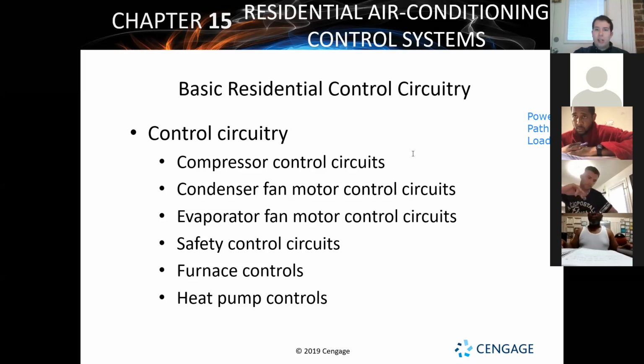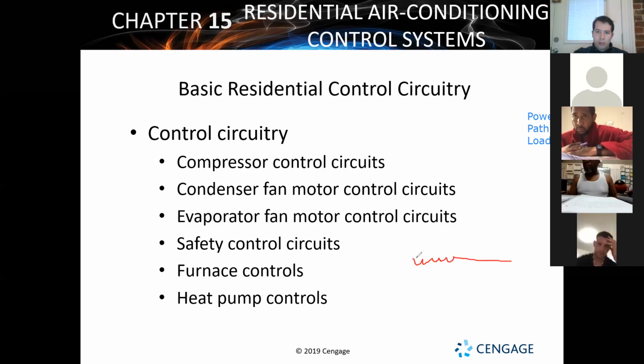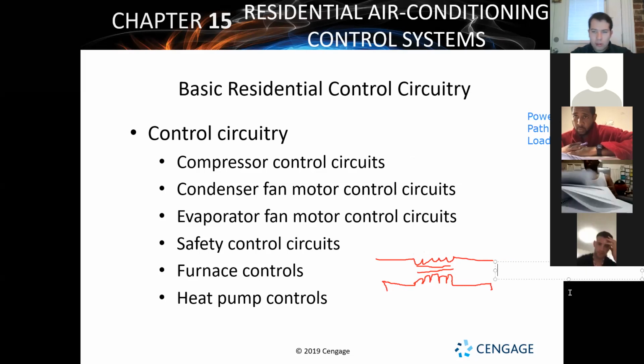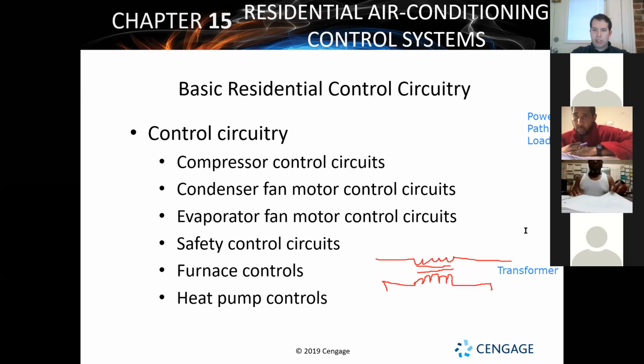So what you're going to see typically for a low voltage circuit, let's see how this goes. You'll have your most common symbol to tell you what is controls and what is high voltage loads. And that's this guy, which is terrible, right in the middle here. That's supposed to be a transformer. So the transformer is going to take, on one side, typically for most residential systems, 120.